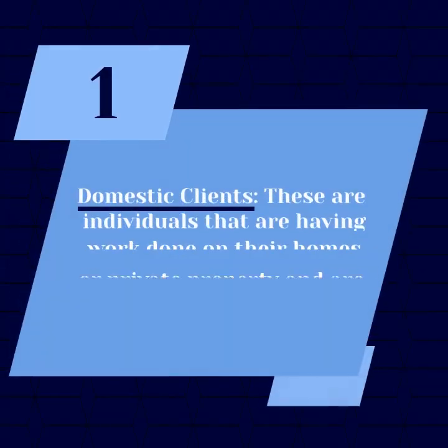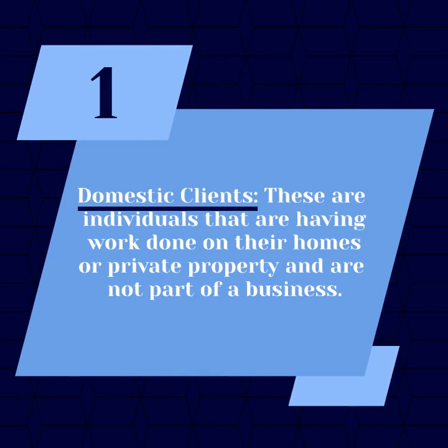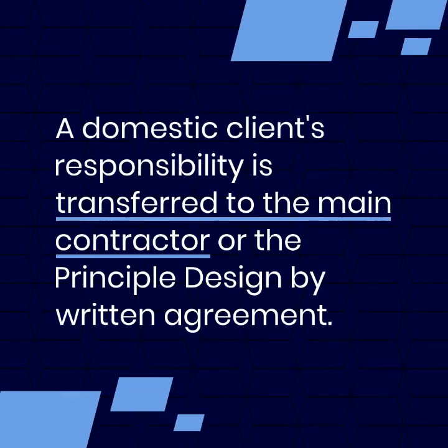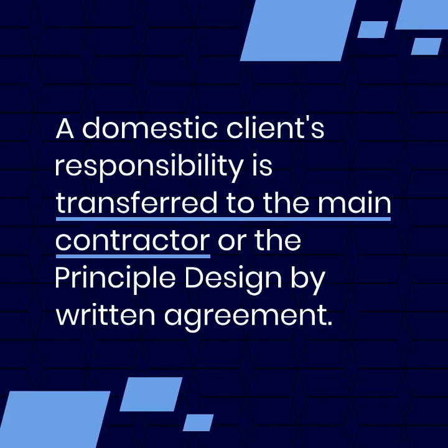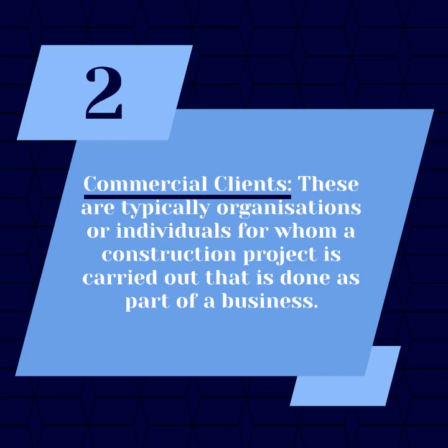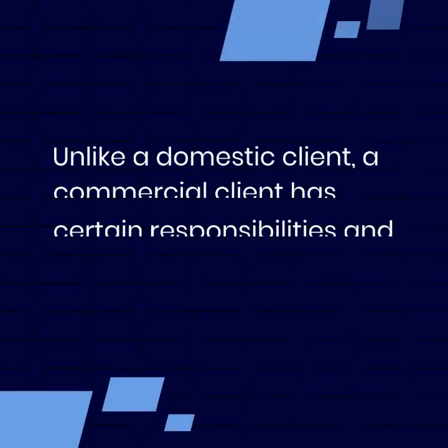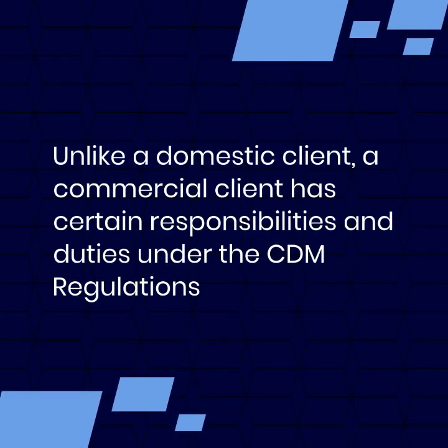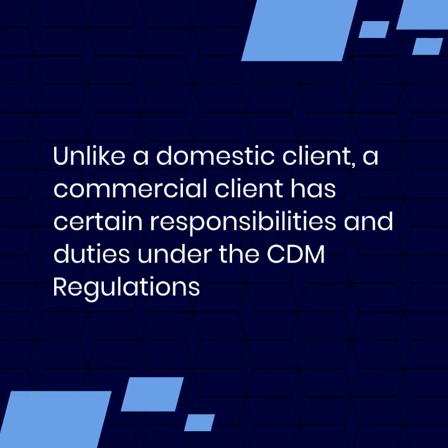1. Domestic clients. These are individuals that are having work done on their homes or private property and are not part of a business. A domestic client's responsibility is transferred to the main contractor or the principal designer by written agreement. 2. Commercial clients. These are typically organizations or individuals for whom a construction project is carried out that is done as part of a business. Unlike a domestic client, a commercial client has certain responsibilities and duties under the CDM regulations.